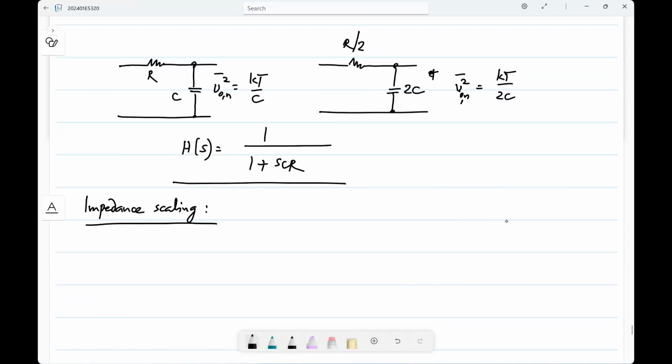I think this may have been part of some basic electrical circuits assignments also. How do you analyze circuits? You write the nodal equations, right? And that has the conductance matrix. So now you can imagine if all conductances scale by the same amount and you have voltage sources, nothing really changes.